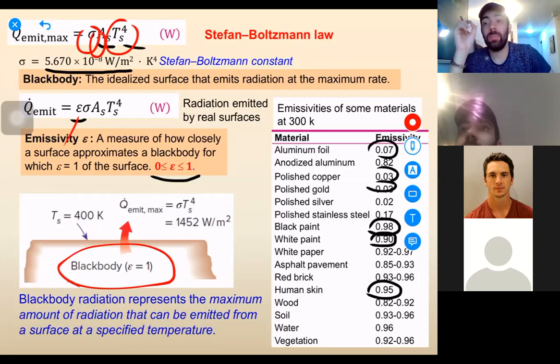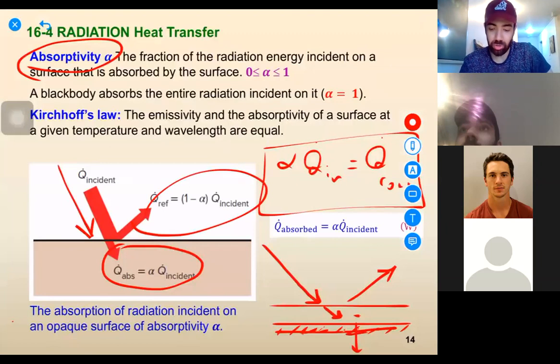When a body has an epsilon equal to 1, it has the highest level of absorption and also emission. When our body is not a black body, then epsilon is an amount between 0 and 1. So it is basically dependent on the amount of epsilon how our heat rate would change.